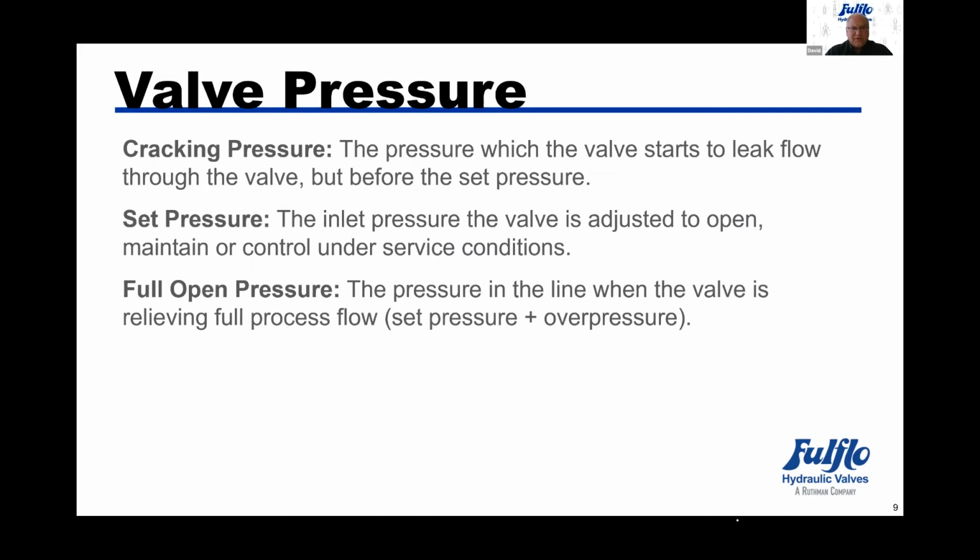Set pressure is the pressure that the valve is adjusted to open, maintain, and control the service conditions. This one you get to choose. You can determine if you want the valve to be set at the operation set pressure or a higher percentage set pressure, but then the springs would be adjusted for that.